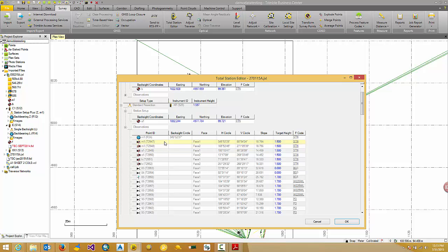If it was open on the left hand side, it was a phase 2. So you can see that the backsight was shot on the point M1 in phase 1 and then in phase 2. Then we turned the instrument to point A1 in phase 1 and then A1 in phase 2 and then B in phase 1 and phase 2, and that completed our station setup, after which we were taking regular topo shots mostly in phase 1 towards these observations.